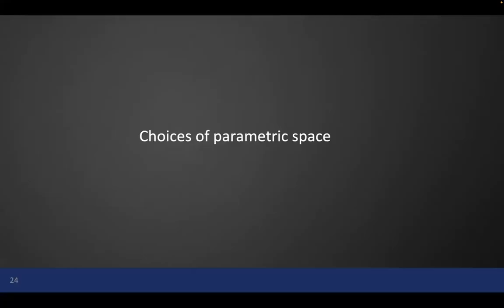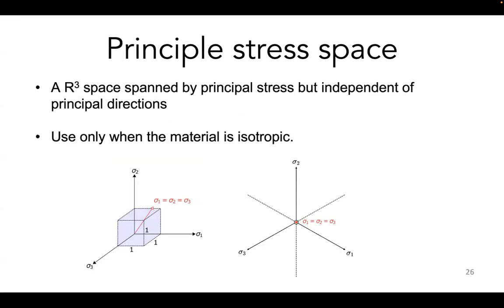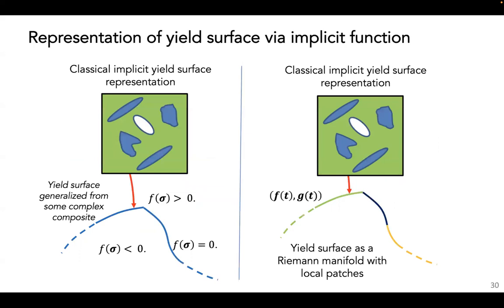One thing that is important is to think about the usage of the plastic model. You actually don't care about the values of the yield function inside the yield surface. If I substitute the stress, I just need it to be smaller than 0. Whether it's minus 1 billion or minus 0.05, I probably don't care, because I'm not going to activate the correction part.